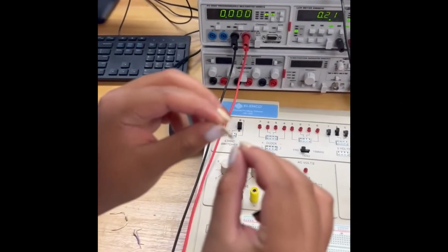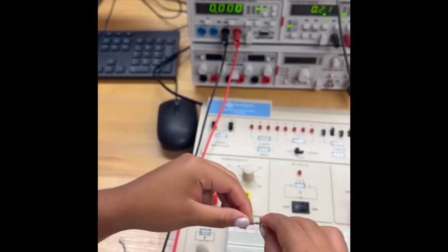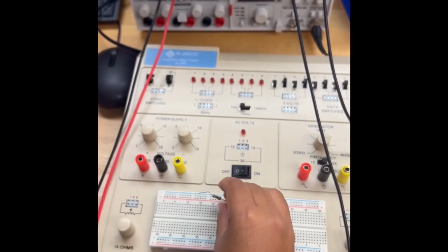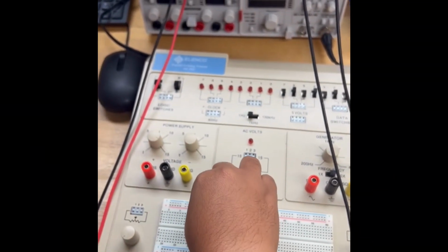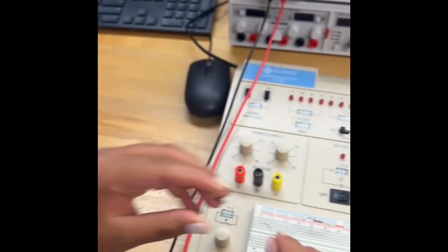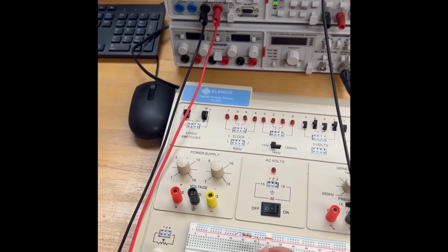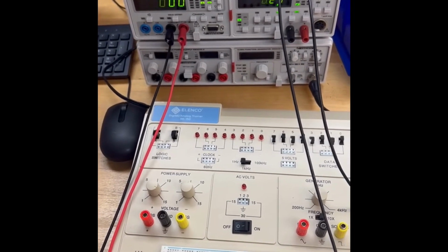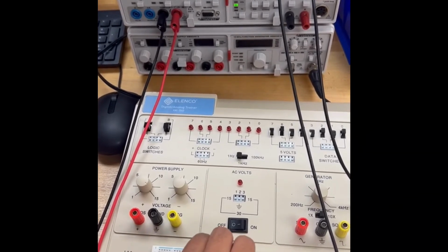Hi guys, my name is Tyra, and I'll be measuring on the bench the voltage source. For this circuit, our first resistor is going to be a 680 ohm. We're going to place it on the breadboard with one of the legs on the dotted red line. We're going to take our resistor 2, which is a 2.7 kilo ohm resistor, and place that in series to the first resistor, leaving the bottom leg on the ground blue line.